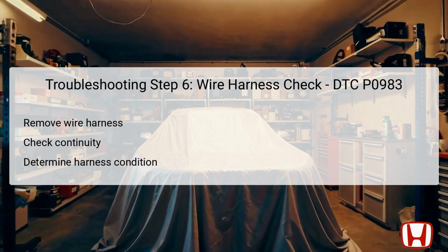In this sixth step of troubleshooting, you'll examine the condition of the Shift Solenoid wire harness directly. To start, disconnect the Shift Solenoid wire harness from the vehicle. Following this, check for continuity between the designated test points. Shift Solenoid wire harness 7P connector number 4, yellow, and Shift Solenoid Valve D 1P connector number 1, yellow. Both connectors should be removed to ensure accurate measurements.